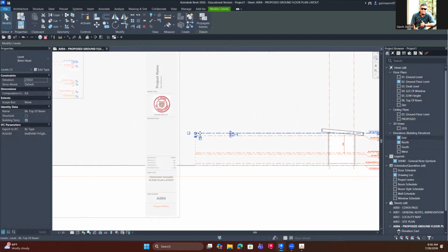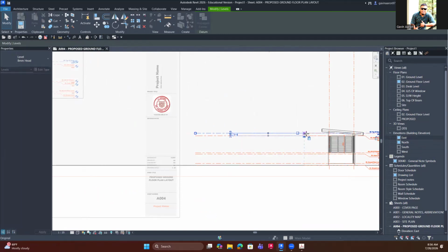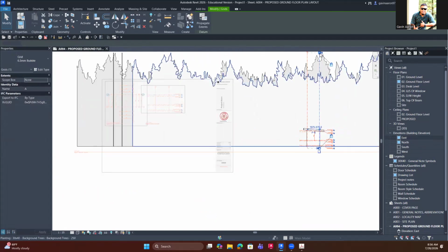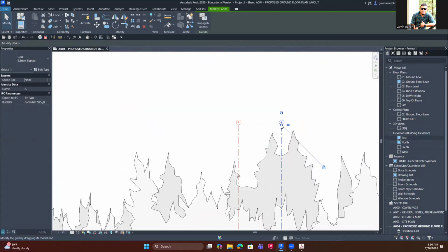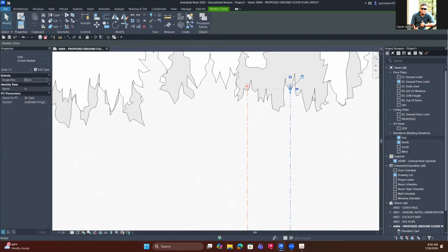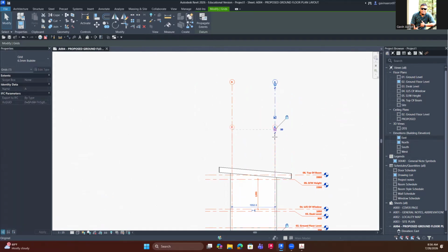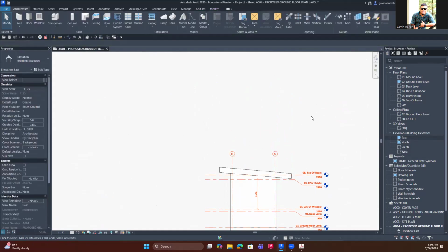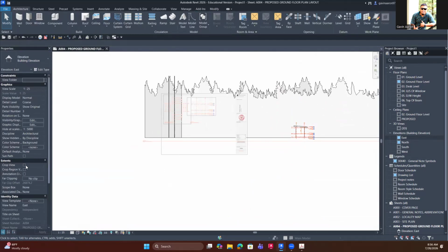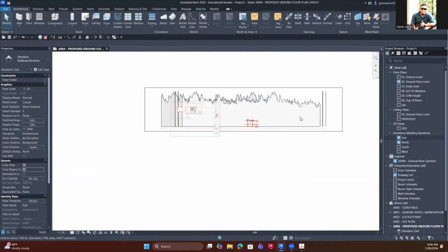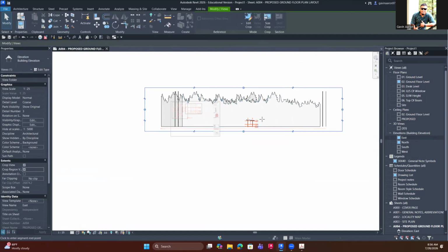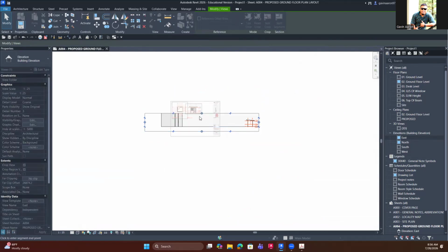It is really important to save space so that you do not have to print a lot of pages when you start printing your drawings. Okay, because you have to know that printing does cost a lot. So if you're doing your own drawings in your own firm, please keep in mind how to save space for your drawings. So once I've removed all the grips for the levels and also the grid bubbles, I'm going to move that viewport or the view.